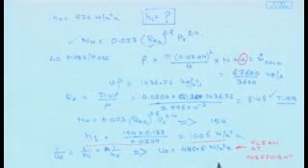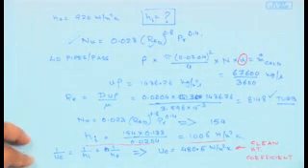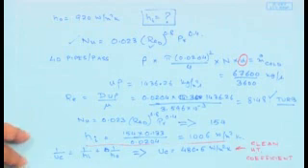So once I know the clean heat transfer coefficient, the next step is to find the heat transfer coefficient for a heat exchanger which has been in use for quite some time, such that the dirt factor resistance, the resistance due to the dirt deposited on the tube and on the outside of the tube, must be taken into account.